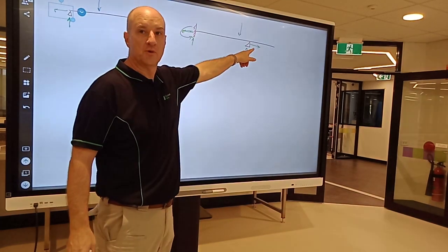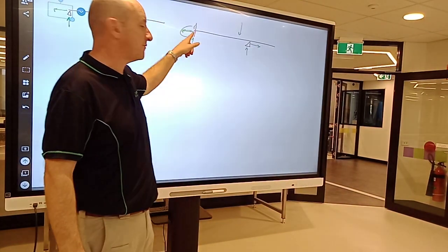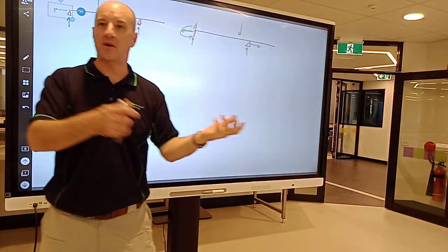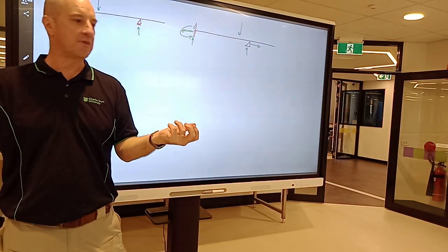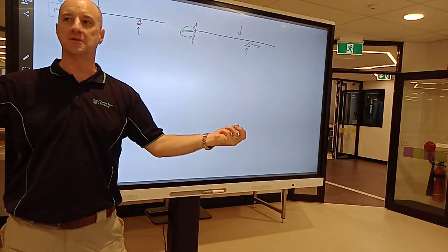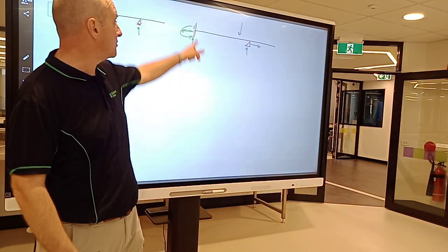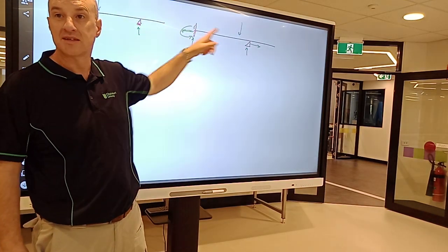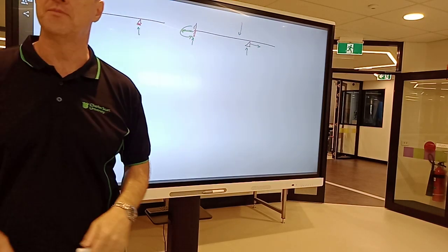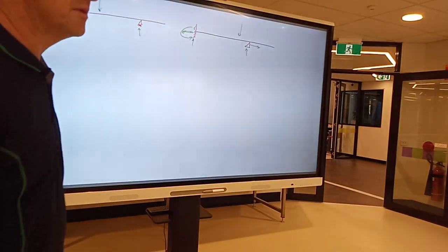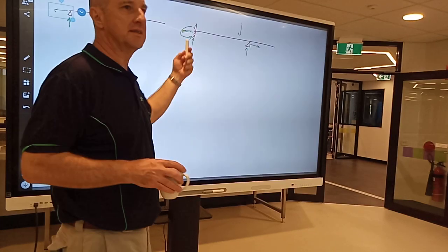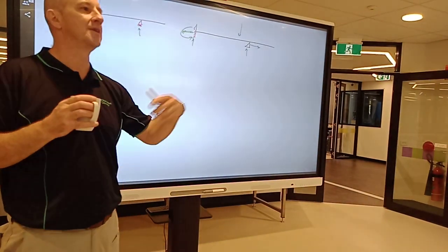See, that's a fixed support over there, it's a pin support. This is a fixed end. Maybe when the fabricators came along and they put the beam here, they had to really stretch it to put it on the bolt holes there. And it's got this tension built into it. We don't know, there's not enough information there. That is statically indeterminate, okay? Statically indeterminate means you can't analyze it easily by hand using normal methods. You get to do that in second or third year.